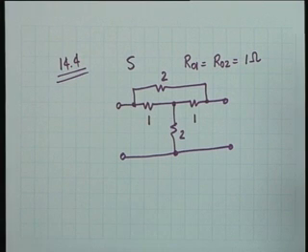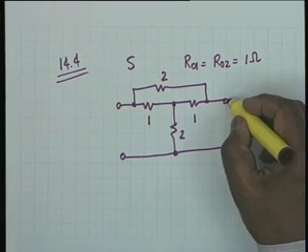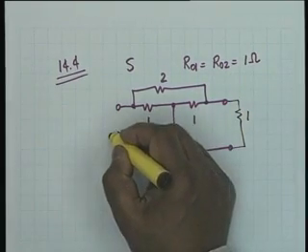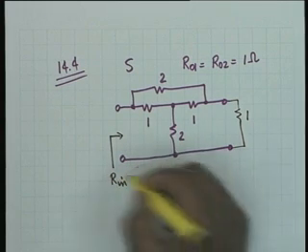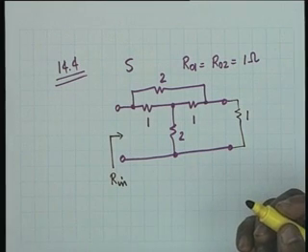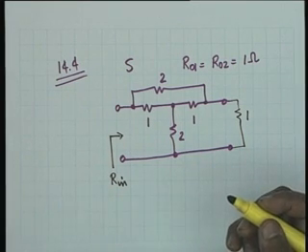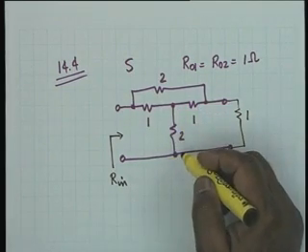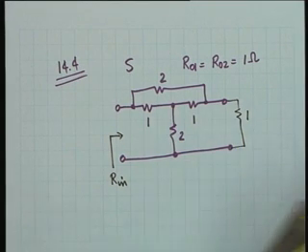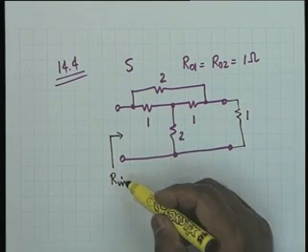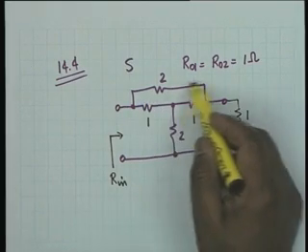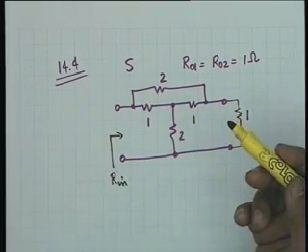For example, for S11 you have to terminate this in 1 ohm and find the input impedance here. Let us say R in, it is resistive. Obviously S11 and S22 shall be equal. Is that correct? Because of the symmetry with respect to the ports, S11 and S22 shall be equal. You do not have to calculate again. But calculation of R input cannot be done by inspection, because there is a bridging here. You have to write either KCL or KVL or use one of those transformations.